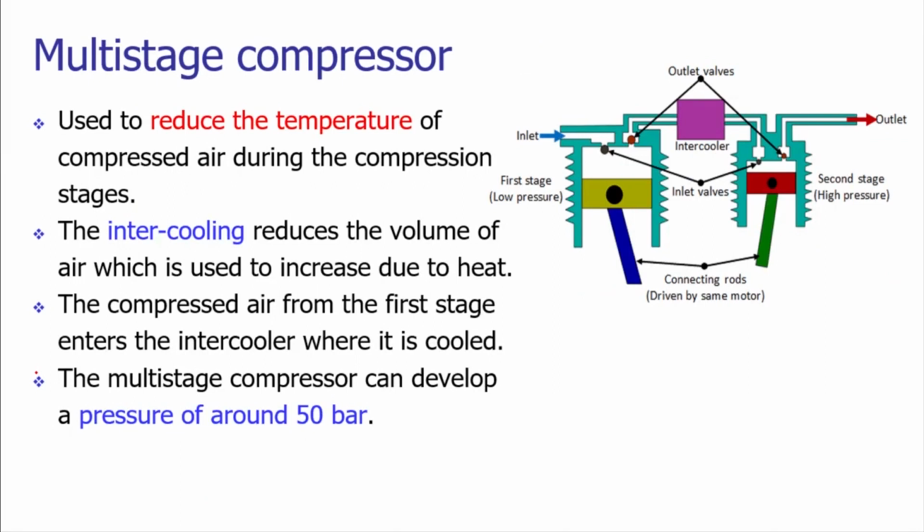Well, in general, for single acting cylinders, to generate a pressure of about 5 bar, the temperature may go up to 200 degrees Celsius. So there is a huge increase in the temperature during the process of compression. To solve this problem and to increase the energy efficiency of these devices, we can go for multi-stage compression.